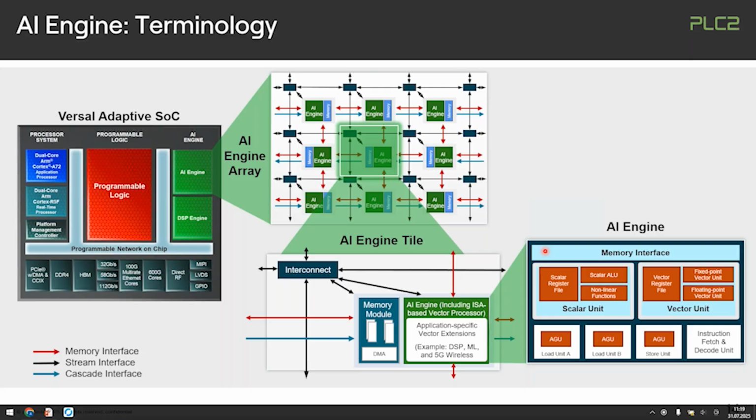So basically you will have a RISC-based 32-bit CPU already within that block. On each and every one of these tiles, you already have a traditional CPU in there with the scalar unit. You have the vector unit itself that is capable of looking at a wide vector of data and interpreting it as different numbers, and it would then feed through the vector unit. And you have all the support functions like moving data between these items internally, or between the memory and the inside of the elements and the different memories. So that's what actually gives us the efficiency.